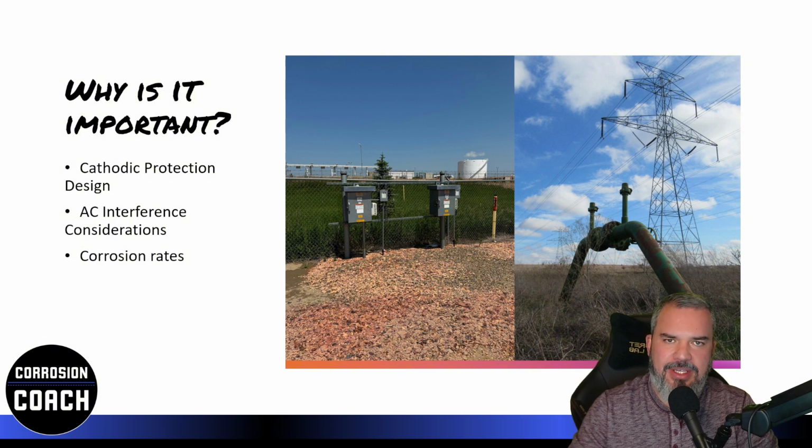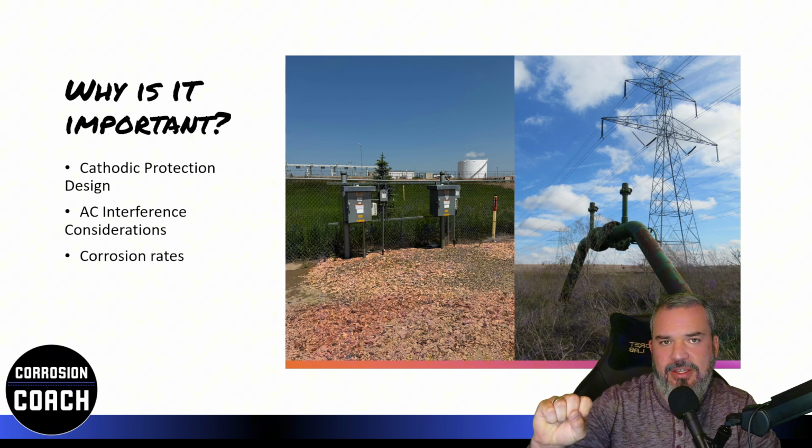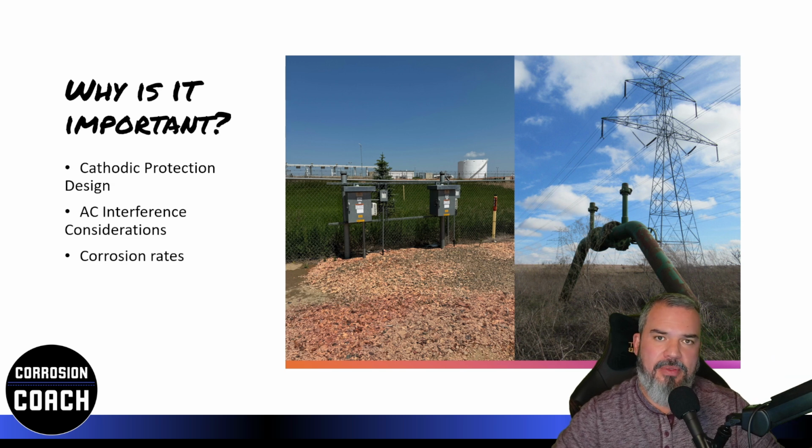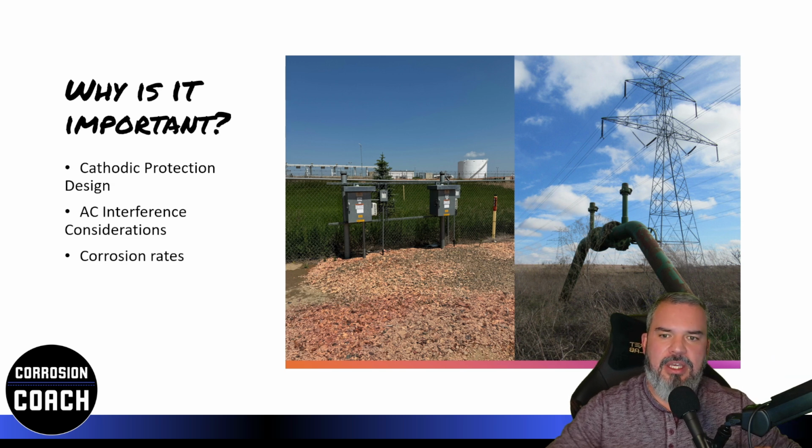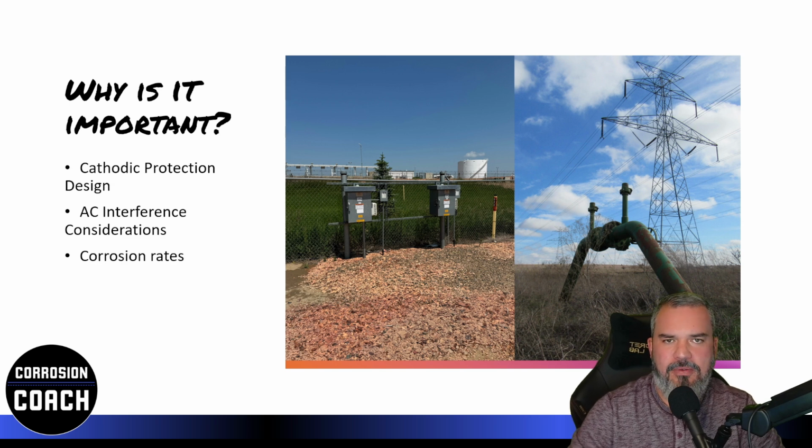Also, in the AC interference world, it impacts some of the same things. It's very similar in that world as well. So we need to know something about the HVAC towers, we need to know something about our pipes, and we need to know something about the environment that it lives in. And again, all that impacts so much. So it can become a very important piece of data that we can assume, but it's much better if we can go out in the field and take some measurements and calculate resistivity, get that data, get it in our database, and make good decisions with it.